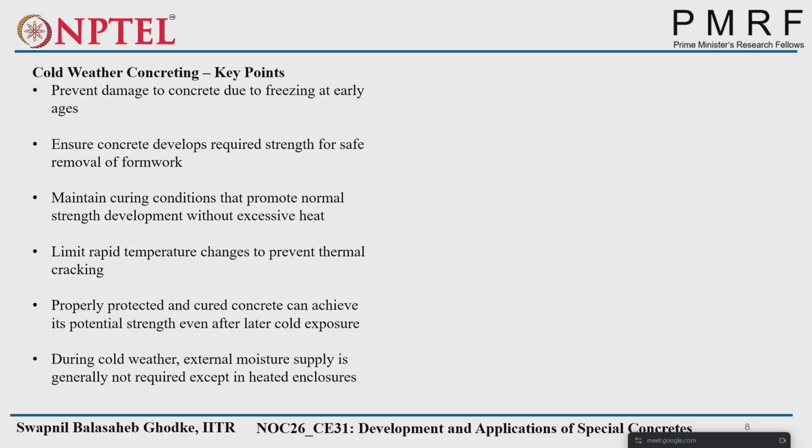Thermal cracking, there is a high chance of getting the thermal cracking. So that's why we have to cure the concrete in such a way that the temperature changes will be negligible in the surroundings of the cast concrete.